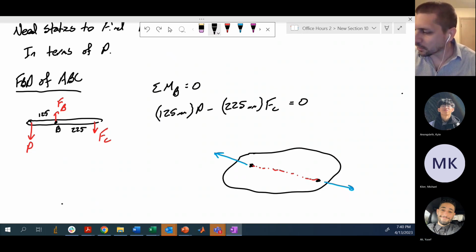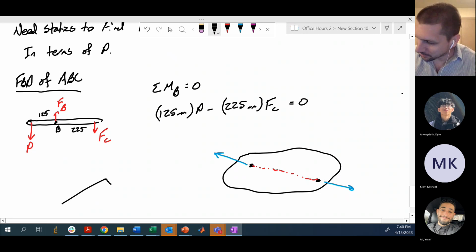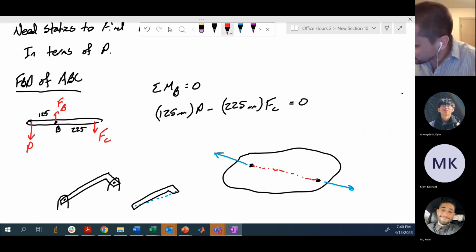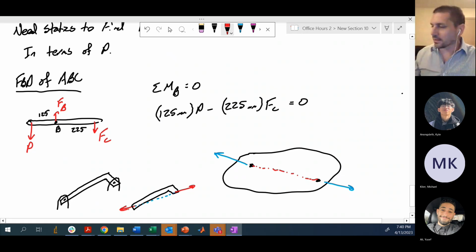One example that trips people up sometimes is an L bracket that looks like this. Let's say I have a point over here and a point over here, and both of them are pinned. This one confuses people a lot, but you could draw the free body diagram of this system where that's your line of action, between those two pins, and you draw the forces this way and this way along that line of action.